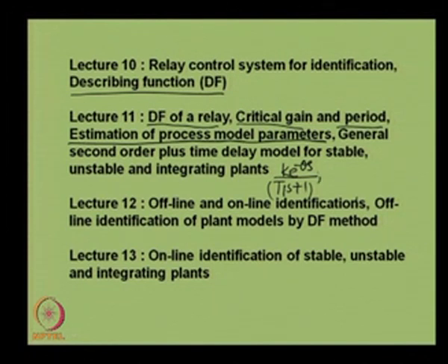Similarly, we can have a second order plus time delay model for the dynamics of stable, unstable and integrating plants, that can be given as k e to the power minus theta s upon (T1 s plus 1) and (T2 s plus 1).